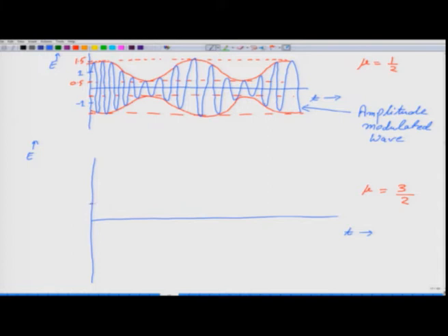So the amplitude of the carrier wave is 1, and of course on the negative side it goes to -1, and the amplitude of the modulating wave, or our signal wave, is 1.5 times bigger than this. So the maxima will now go to 2.5, on the negative side also it will be at -2.5, and the minimum of this amplitude modulated wave, since we have considered its amplitude as 1.5, will go to -0.5 and similarly to +0.5.